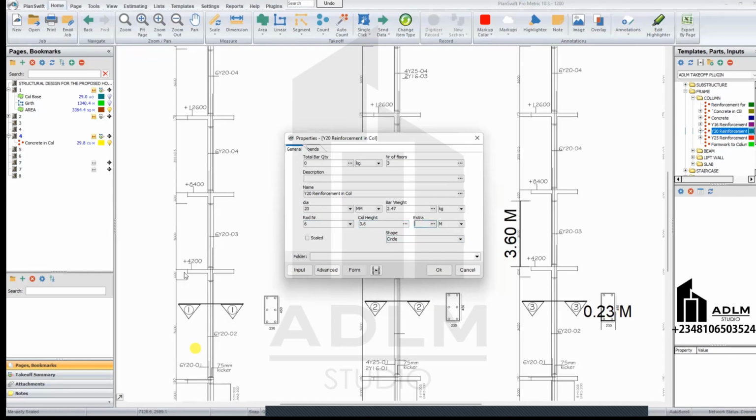Now plus the extra, we have the 0.6, that's from the bottom beam to the slab. Plus, can I have your extra that will join the other floors to it? Let's just say extra 0.8. Now this is just 3 floors. So you have the number of this column, that will be 8 numbers of this column times 3 floors. That will be 8 times 3 floors.